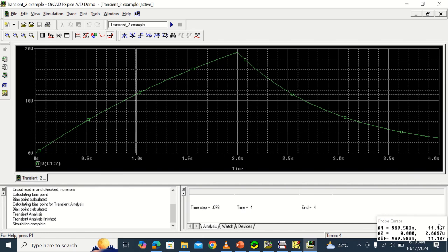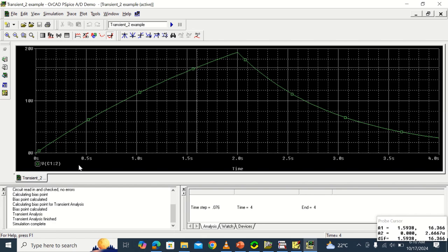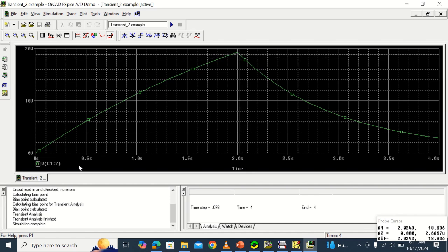The second part here is the y-axis value, that is the voltage. Okay, so t equal to 2 seconds is here. So you can see here t equal to 2 seconds, and the capacitor voltage is 19.294. 19.294 volts is the capacitor voltage. You can mark this point. That is the first part of the question.